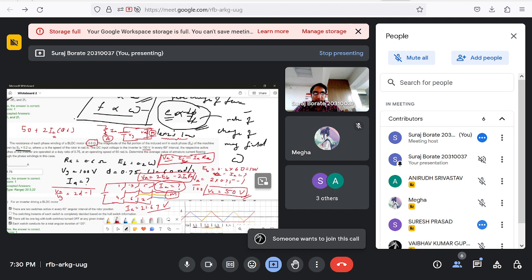Okay, and one of the good things about this motor is that BLDC motors are an essential component in building something called back drivable actuators. Okay, so remember these words. These are very important words when you start designing your own robots. Okay, so what are back drivable actuators? It means that when there is some disturbance at the load side, you are able to move the motor backwards.